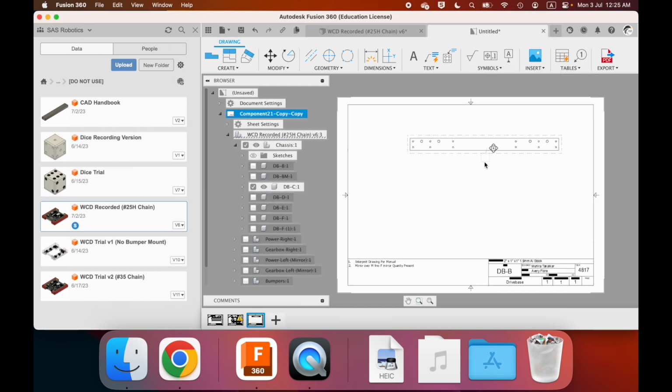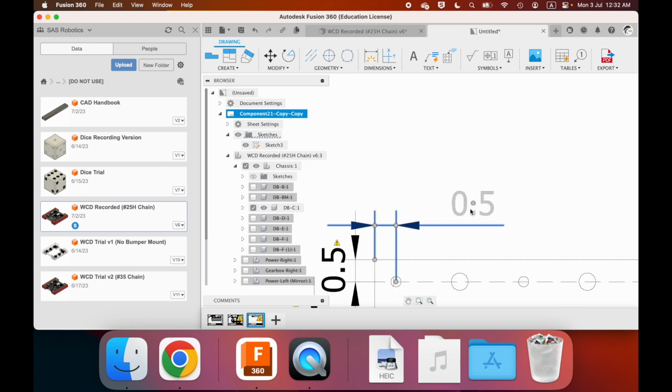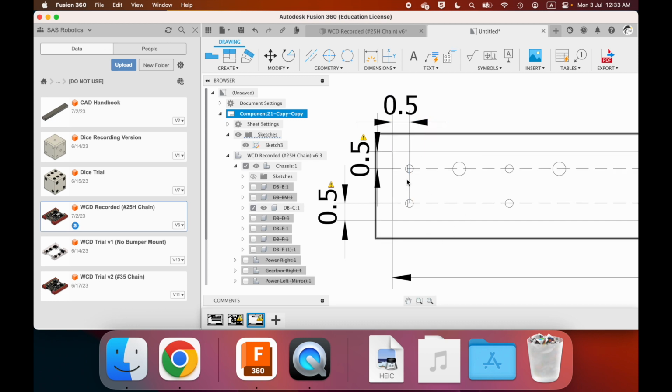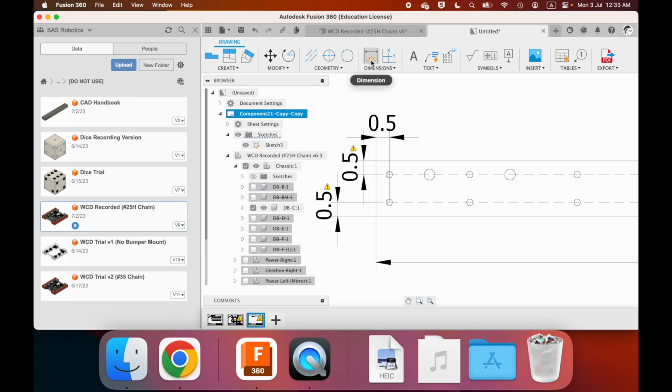Okay, one thing I didn't make clear, you want the thin view on top. And preferably the fillets the other way. Okay, so this is the first view. Another thing, you always draw the dimension to the lower hole, in this case here, so that line just goes through both, so it's very clear both are 0.5.